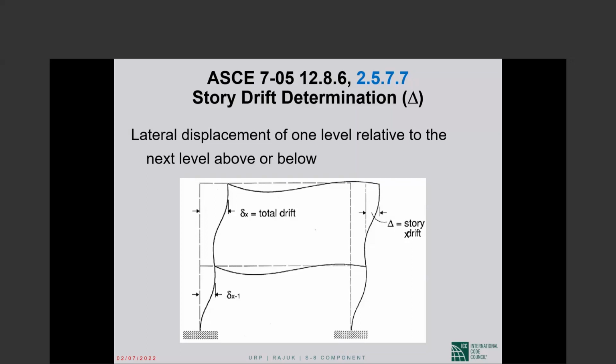Seismic design in our codes is essentially about life safety. Occupants will at least be able to escape before a structure actually collapses. That is pretty much our aim. We are not trying definitely to prevent damage to our structure or anything like that.